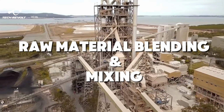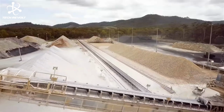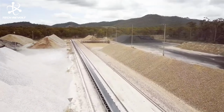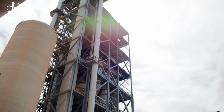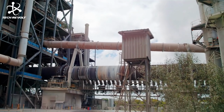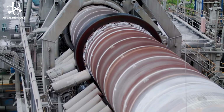Raw material blending and mixing. After crushing, the materials enter the mixing phase, where they're combined in carefully controlled proportions to create what's called the raw meal. The chemical composition needed for a specific cement is roughly determined by carefully selecting and controlling the raw materials sent to the crushing and grinding plant.